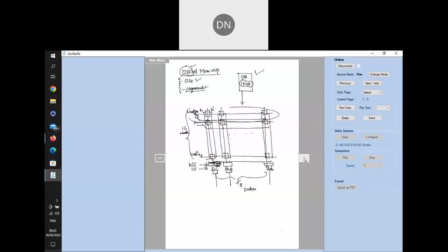Any one of the words I'll be selecting based on the address supplied by the processor. Now, how many addresses are there? 16 addresses, which means I require 4 address lines. They are called A3, A2, A1, A0. With these 4 address lines, 2 to the power of 4, that is 16 combinations, are there.